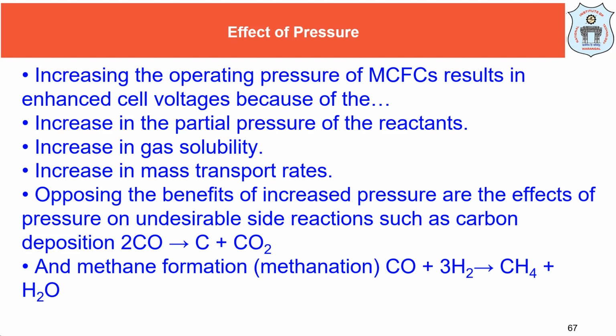Okay, and opposing these benefits of increased pressure are the effects of pressure on undesirable side reactions that may take place, because when you have carbon monoxide under high pressure, there may be carbon deposition, 2CO giving C plus CO2. So carbon formation takes place, which will get deposited and block the catalyst surface.